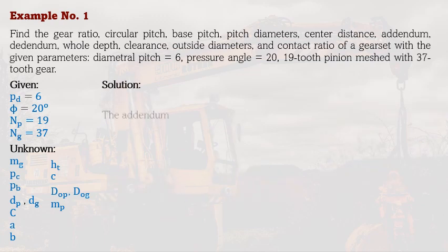And then we will solve now for the addendum. The addendum is just the portion of the tooth that extends above our pitch circle. Since we already have the pitch circle, we need to compute the addendum so that we can draw the upper portion of the teeth. The addendum is defined in our AGMA standard table as 1.0 divided by PD.